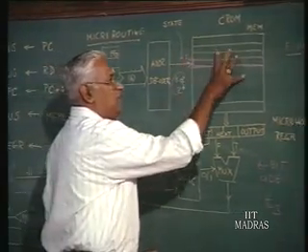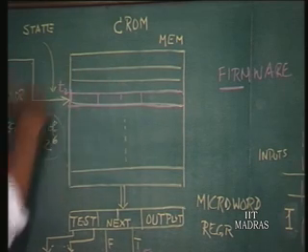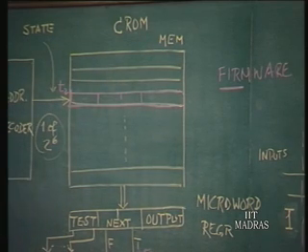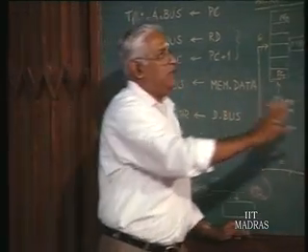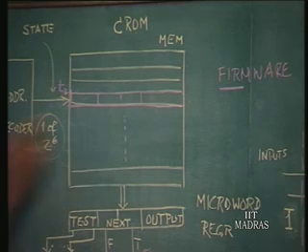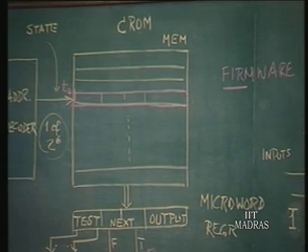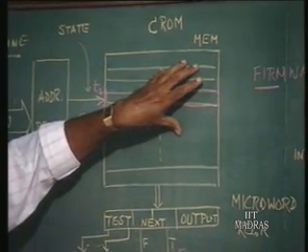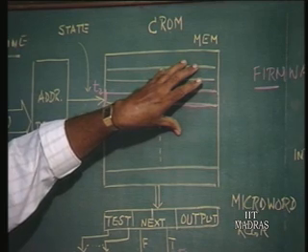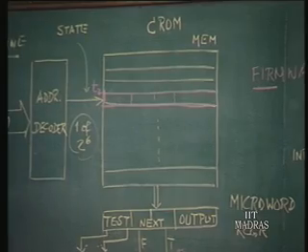Now if you pull out these codes and put in another memory with different codes, the whole behavior is going to be altered. So the read-only memory, through its codes, actually captures the behavior of the whole machine. Good. And since one can change it, but one doesn't change just like that, when one can change, we say it is firmware.